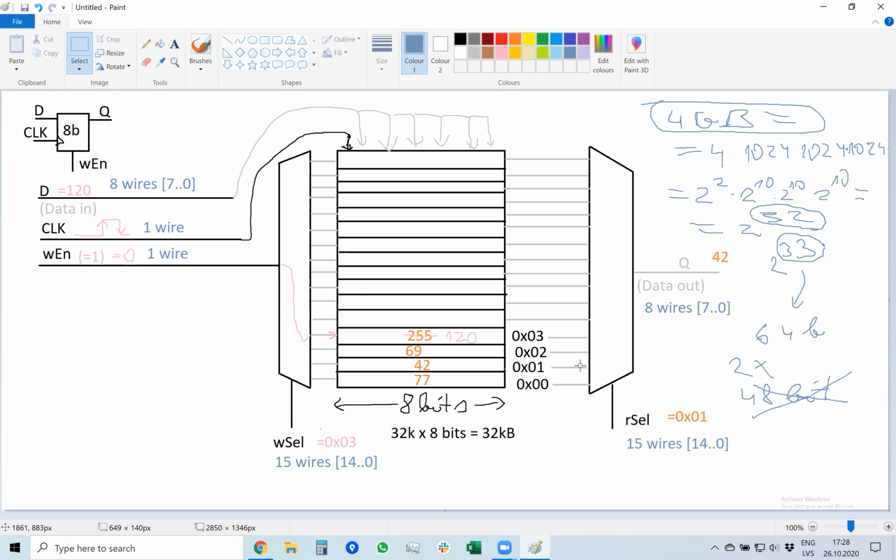So if we're talking about ARM processors, which are 32-bit processors, their memory is generally like this, but with some superpower in the following way. ARM processors actually have data out 32 wires, and they can select if they want to read just 1 byte, or 2 bytes.